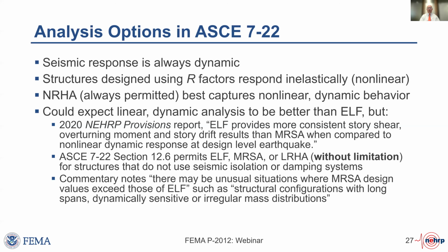Our approach to design in the US and in most countries uses R factors or some other similar method to say that effectively we can't afford to design everything to remain perfectly linearly elastic for the greatest magnitude of earthquake that could possibly occur. Instead, we accept societally and then professionally that we could have some inelastic behavior, as long as we don't have collapse and as long as we don't have too great an impact on life safety.